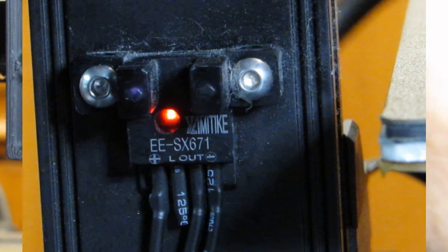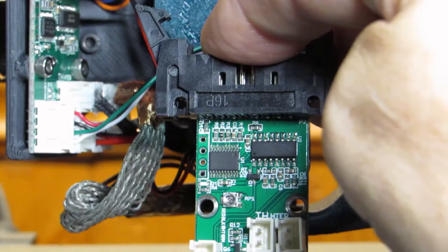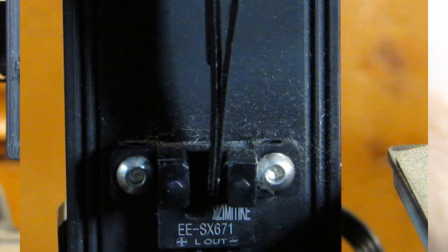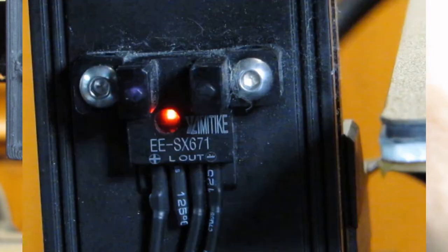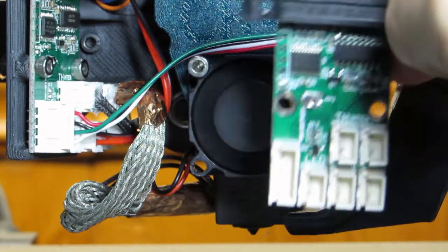Marlin was programmed to understand that the optical switch says either the probe is active or it's not. If the probe is active, listen to that signal and understand it as Z-min stop switched on, active. If the optical switch probe is not active, ignore what's coming from the nozzle probe because it doesn't matter. It's probably printing and banging into things and it's irrelevant. We're not looking for the bed right now. So that's the importance of the optical switch. But that's a really high level discussion.